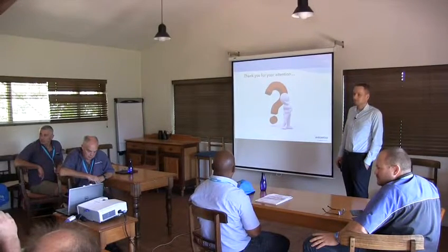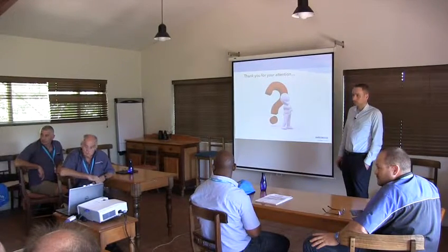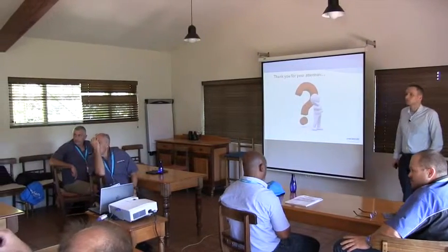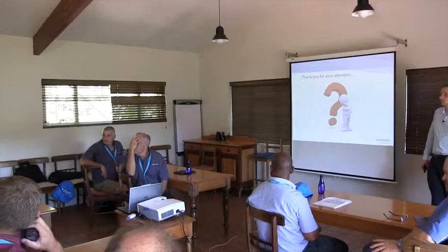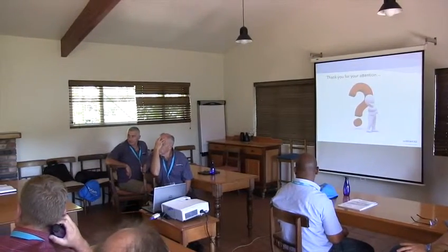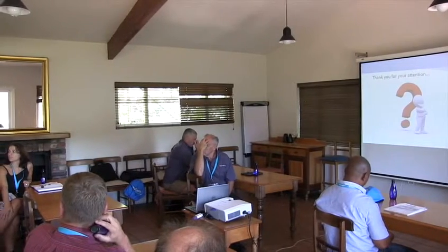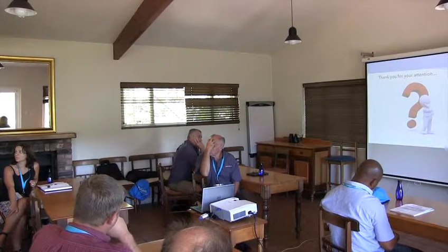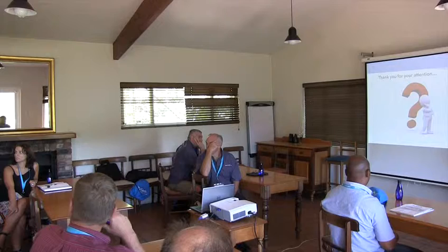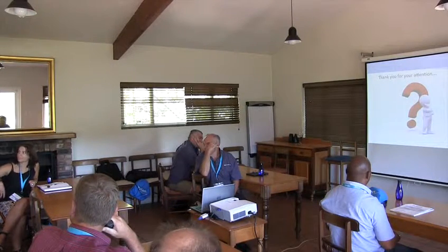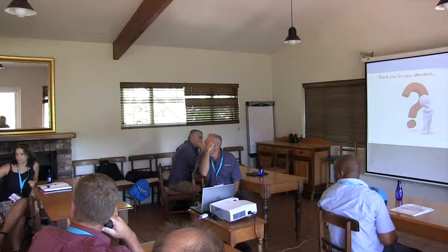If you can get the guys to change over to UV, the downfall on this is that, like Lucinda said, there is a residual chlorine that needs to be done. And the only reason for that is because we do upstream disinfection. We disinfect it at the treatment works. Yeah. Anything downstream is open for, dare I say, reinfection? Reinfection is the right term.